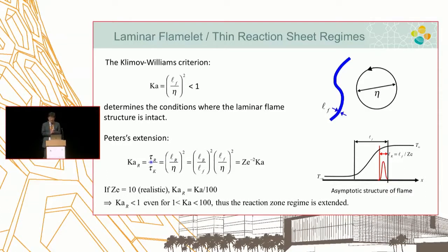So every flamelet school person wants to justify that the flamelet assumption is valid for a wider region. So he came up with an idea: even if some small scale eddies penetrate inside the flame, wait a minute, asymptotic theory tells me the reaction layer is much thinner, by a factor of 10. So I still have room for having small eddies up to this big.